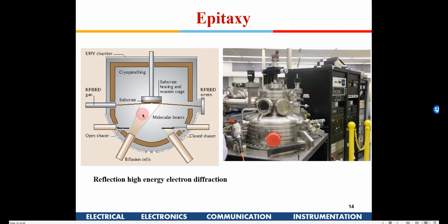Okay, so you could have silicon and you could have germanium, or you could have both of them, and you can control the amount of silicon germanium which is being thrown onto the wafer, so that you have the required silicon germanium concentration, right? When silicon and germanium are used together, they create a little bit of stress in the lattice, which in fact increases the mobility. That you will probably learn in detail in your CMOS technology classes. I am just giving a rough idea.